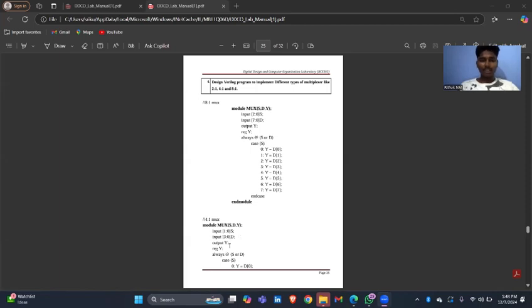In the third line, I have declared D as a 4-bit input signal. The 4 bits of D are D of 0, D of 1, D of 2 and D of 3, where D of 0 represents the first data input, D of 1 the second data input, D of 2 the third data input and D of 3 the fourth data input. As you all know, when we consider a multiplexer, there will be a single output. So to name that output, I have considered Y.